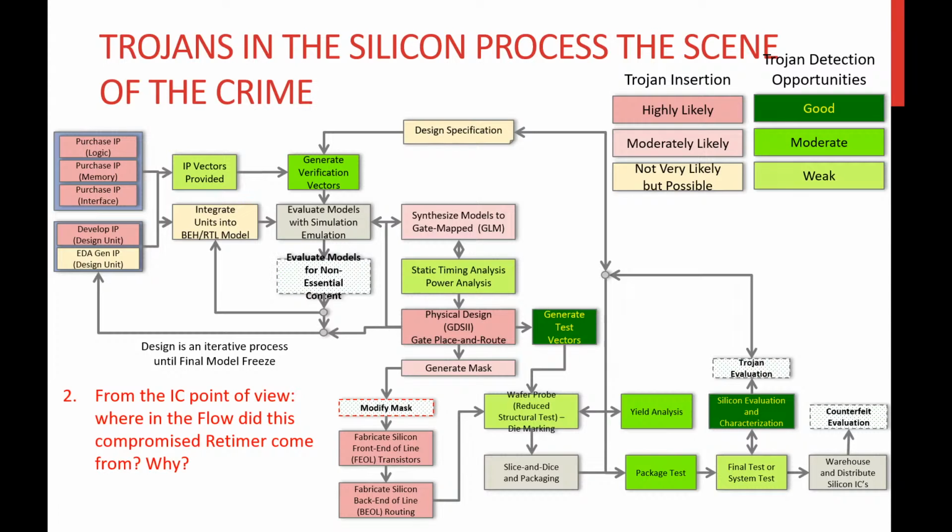The easiest, given that this is a fab, is that there is an RTL, a register transfer level model block of the Trojan logic that must go through synthesis and place and route, or that there is a physical macro of the Trojan and trigger circuitry that already exists and is placed, attached, and connected during physical design.